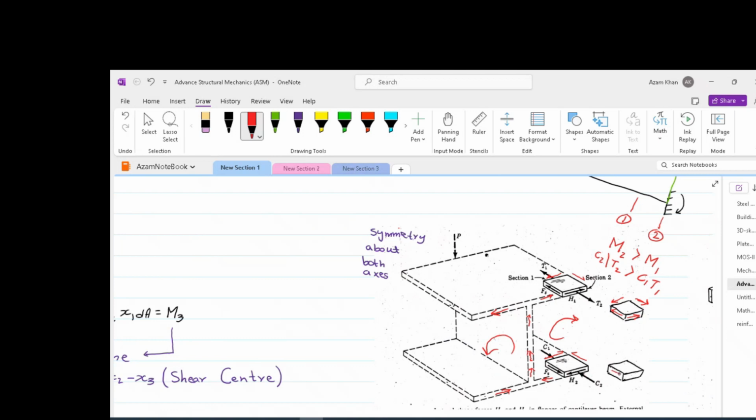So the force Fs will be in the direction opposite to C2. This force will have then the opposite force on the adjacent face. These two forces, which are equal, are causing a counterclockwise rotation. This counterclockwise rotation will be balanced by a clockwise rotation.